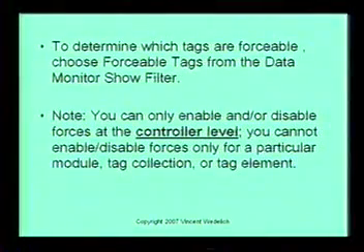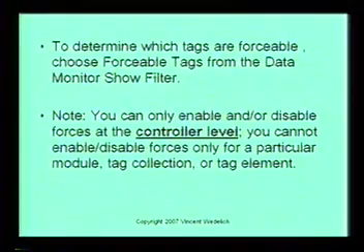Okay, next, to determine which tags are forcible, choose Forcible Tags from the Data Monitor Show filter. Note, you can only enable or disable forces at the controller level. You cannot enable or disable forces only for a particular module, tag collection, or tag element.